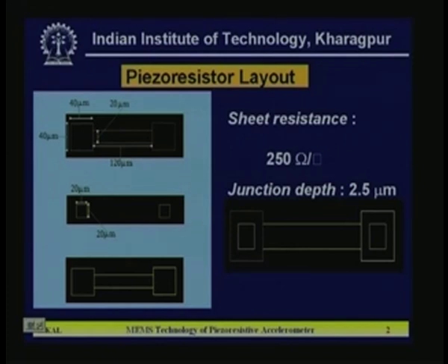But one thing I would like to mention is that in any diffusion technique the resistance variation after fabrication is nearly 10 to 20%. Most ICs are designed in such a fashion that even 20% variation of the resistance values will be accepted by the designer. That means the design should be robust, so that with that resistance change the performance of your circuit will not be hampered much. Similarly here also we assume even 10-15% variation, and the complete circuit should work.